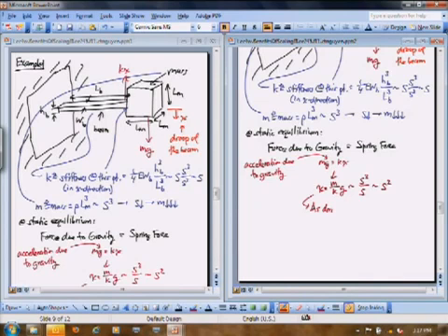So we're talking about the fact that when I make things smaller, if that thing was drooping before, it probably is drooping much less just because I made it smaller. Even though the ratio of dimensions, the initial ratio of the sides of the box to the length of the beam, is still the same. It's just that everything is a lot smaller, and because everything is a lot smaller, that beam effectively is a lot stronger. It can hold that thing up with much less droop.